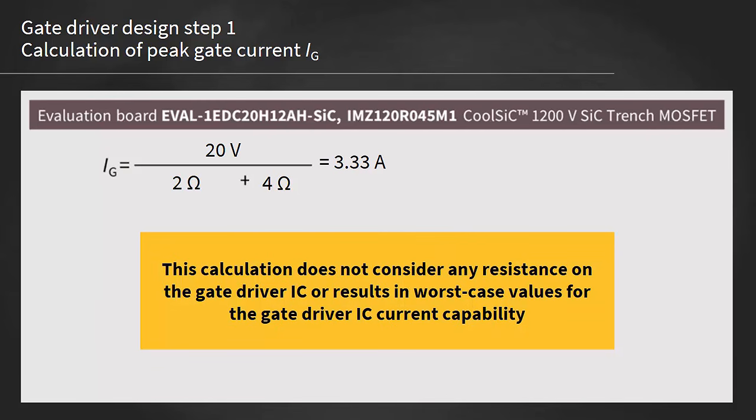Keep in mind that this calculation does not consider any resistance in the gate driver IC, or results in worst case values for the gate driver IC current capability.